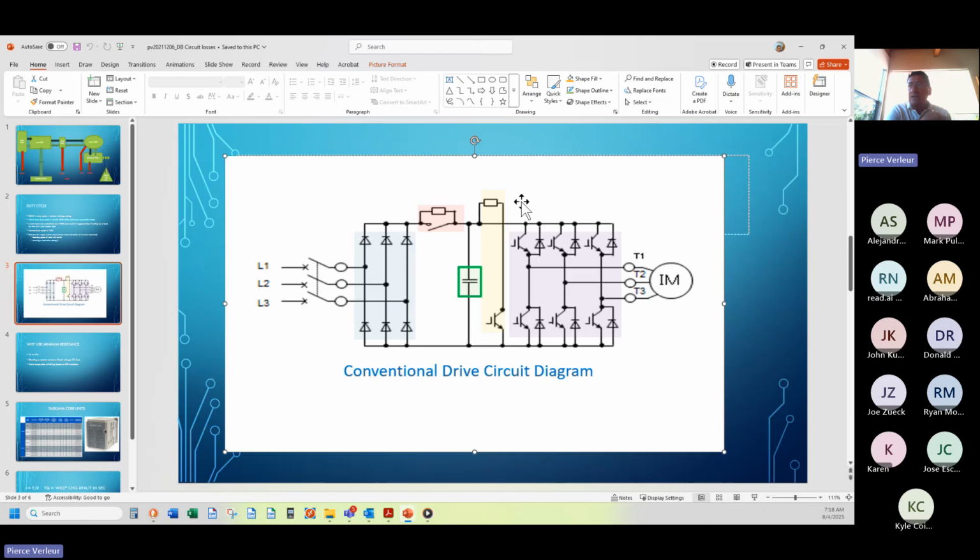Now, I'm going to correct something I said a moment ago. That switching doesn't start at 720, 730. It actually starts at 760 volts DC. My mistake was that the hysteresis, where we shut this transistor off, is around 720, 730 volts. So at 760 volts, motor regenerating, we start to send energy to the resistor. We shunt this resistor across the DC bus. It's a simple buck battery circuit.